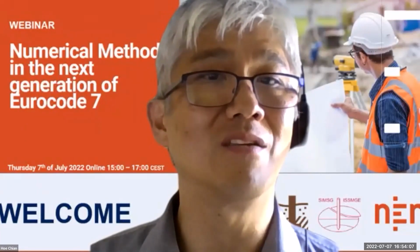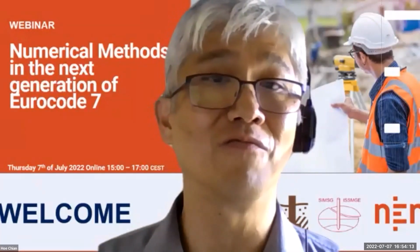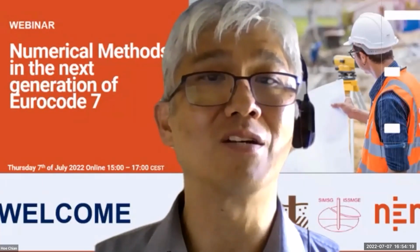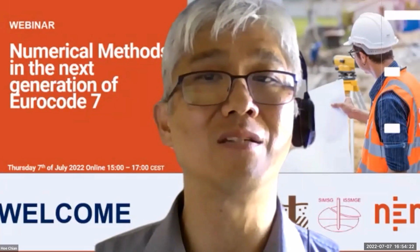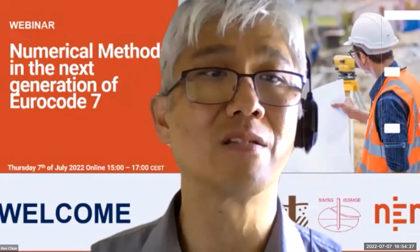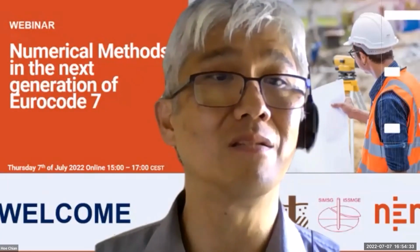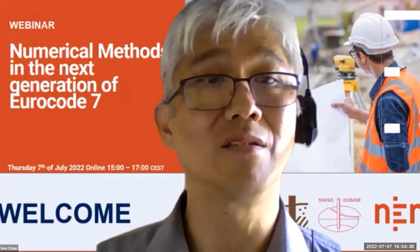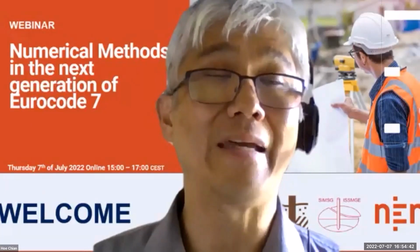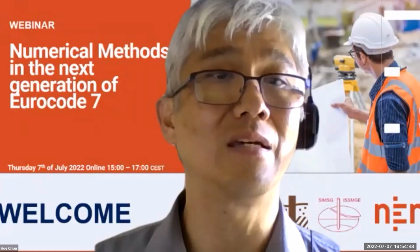So I would say that if you really can't get a factor of safety of more than 1 after applying your factor, and you investigate your model and it is doing the right thing, but not able to get convergence and you get the failure mode happening in the model, it's likely that you are not achieving your partial factors requirement. So you need to change your design to get to a converged model. That is assuming that the model runs in a sensible way, and you see that yes, there is a failure.